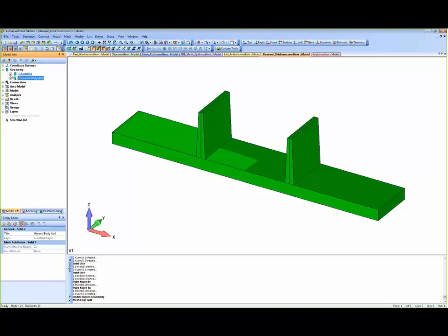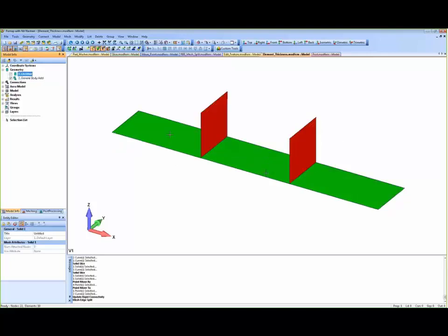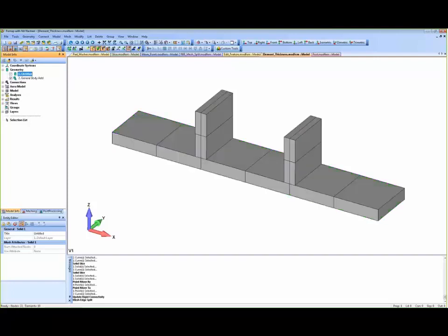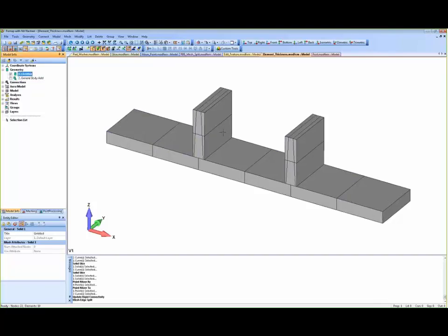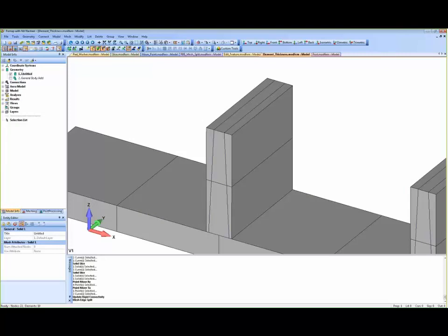We've gone through and we've mid-surfaced it. There's our mid-surfaces that are associated with our solid geometry. And not only that, but we've meshed it. Right now I have the thickness on, thickness and cross-section, so we're looking at the total thickness. So now if we compare that to our solid, right here it's not matching up very well because, again, all of these elements are looking at that one property card, and that property card has an incorrect thickness for our tapering fin. So to fix that,